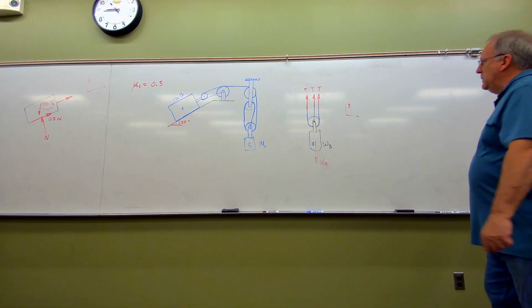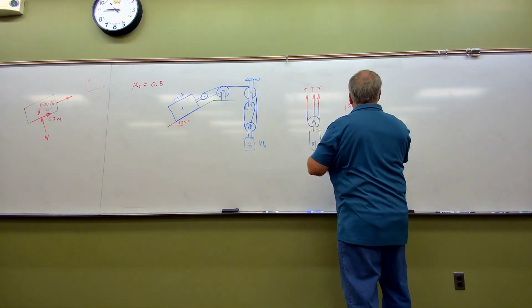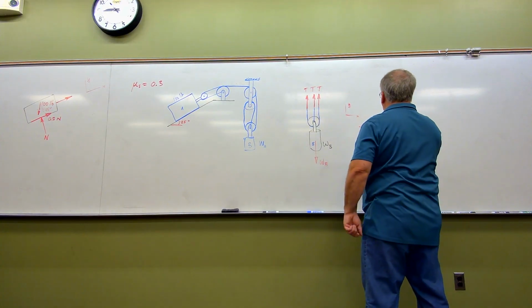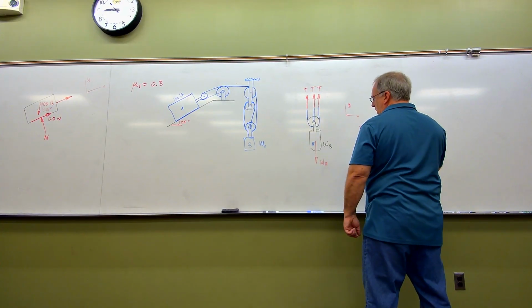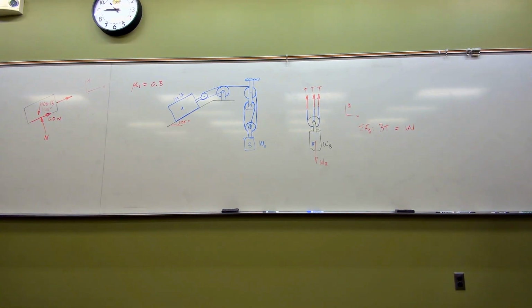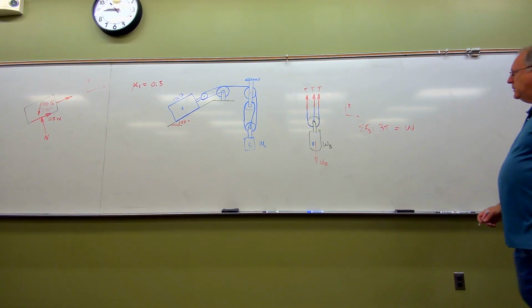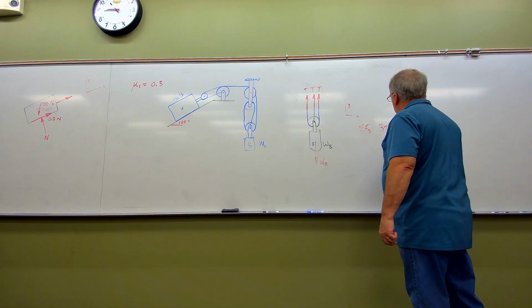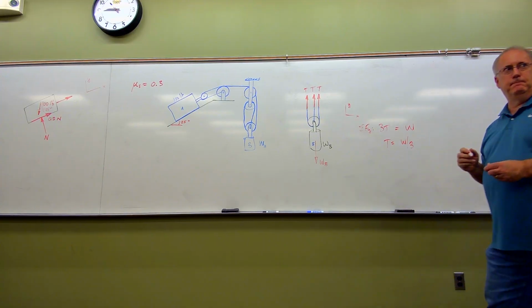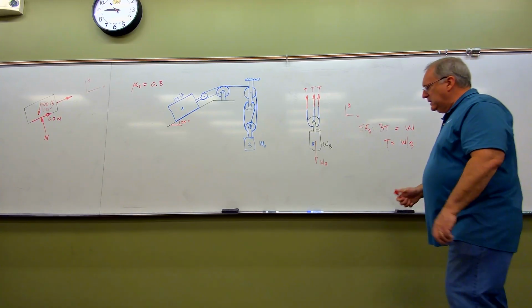Now that also means that if I sum my forces now in the y direction, I'm going to have 3 times T here is equal to the weight. And this leads to something very, very important. That means the tension in each cable is nothing more than the weight divided by 3. And that leads us to a principle.